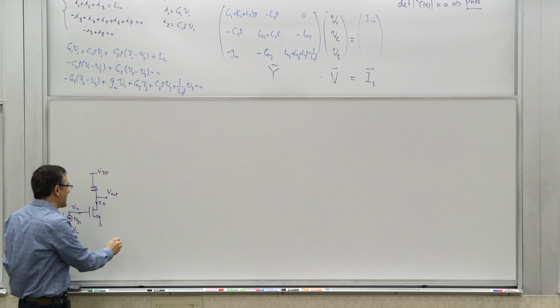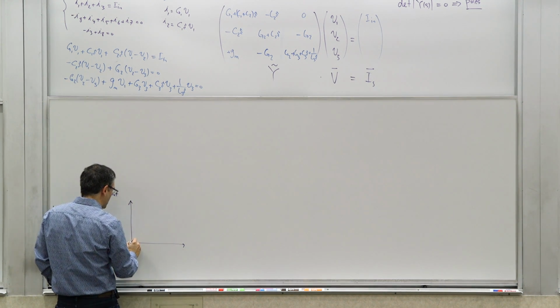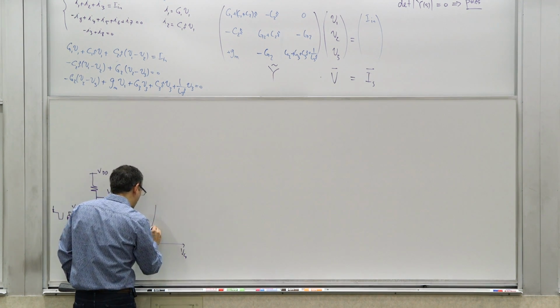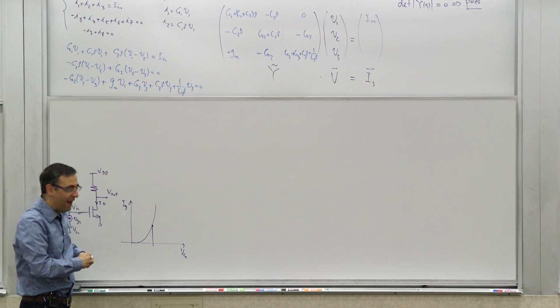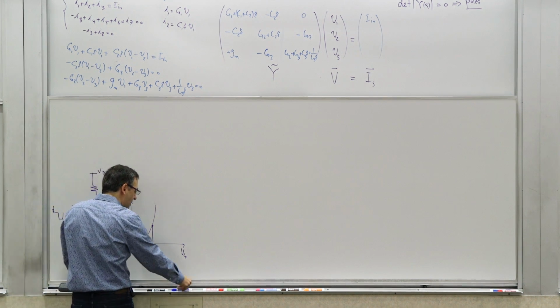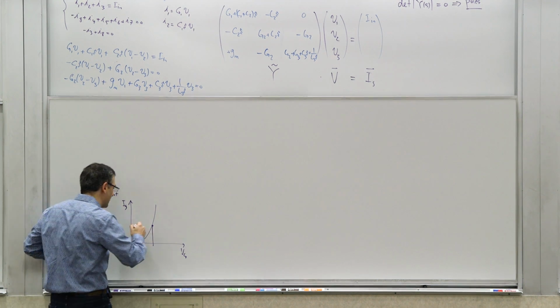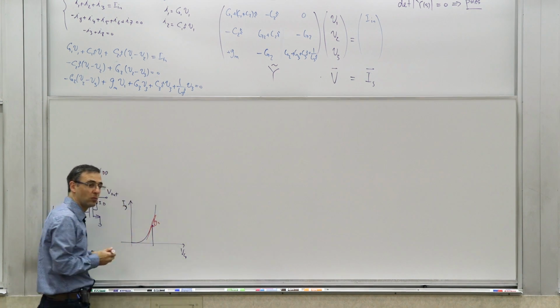Once you define what ID and the VGS are, you can define things like gm. So you can say this is ID versus VGS, and at that point, I'm here. Right? And then what do you do with that? Well, okay, I'm here, so now I linearize it around this operation point. I do a perturbation. I say, okay, this is my gm, the slope of this line.